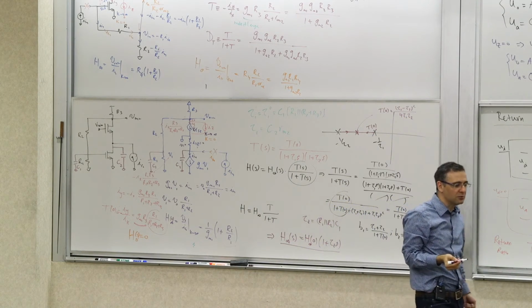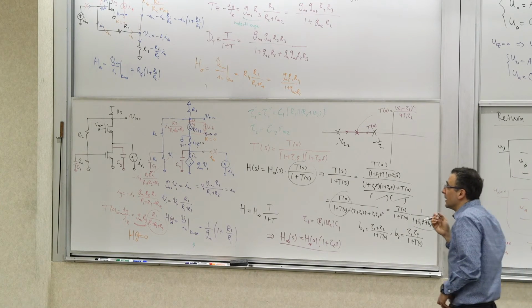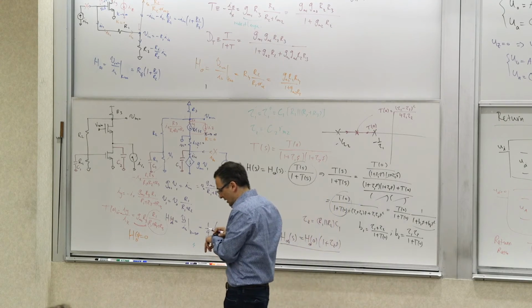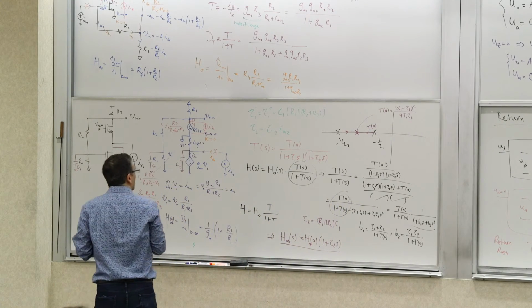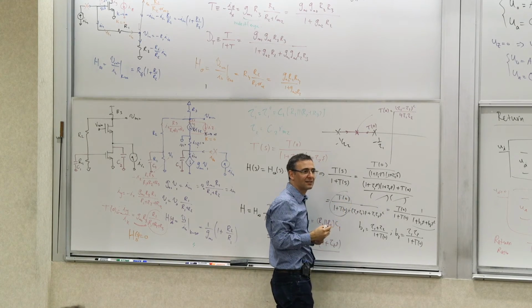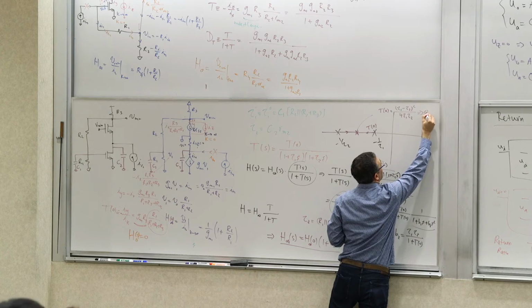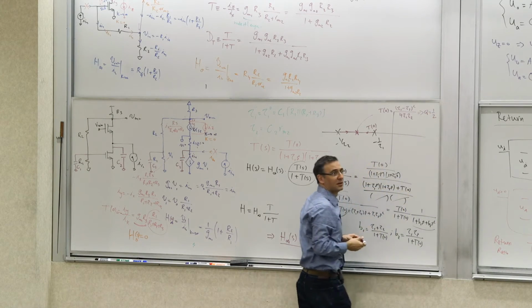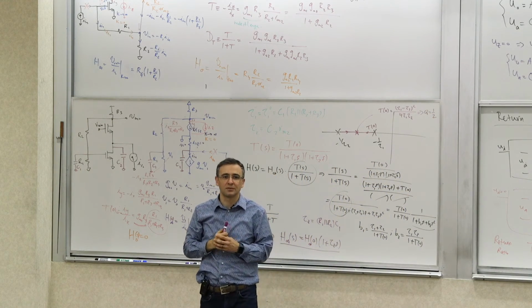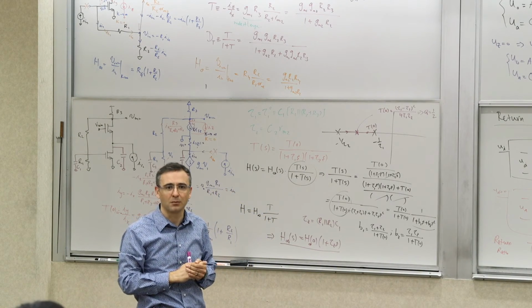It's a simple quadratic equation, you can evaluate it that way. So at that point, they hit each other. And this is where Q is 1/2, a quality factor of 1/2, which is the borderline for poles becoming complex.